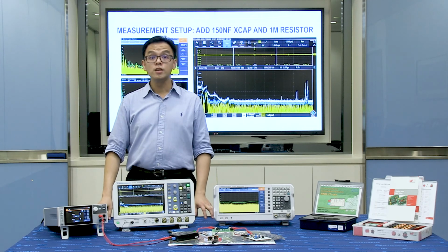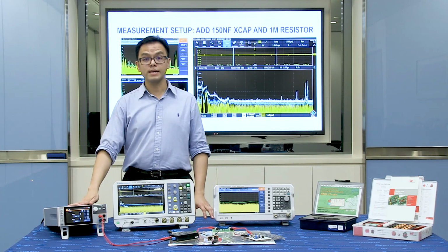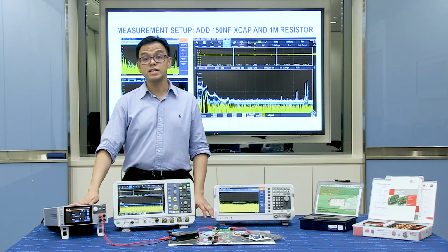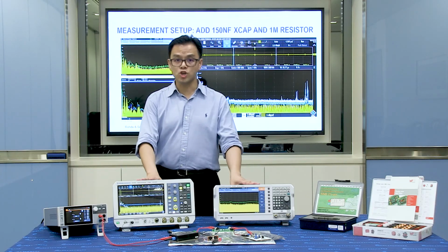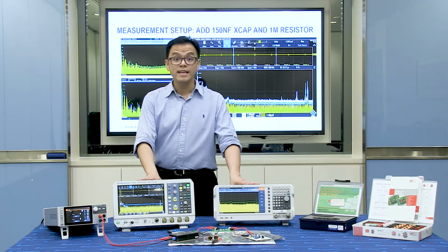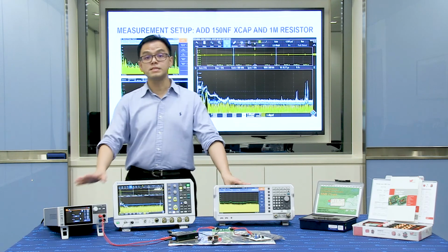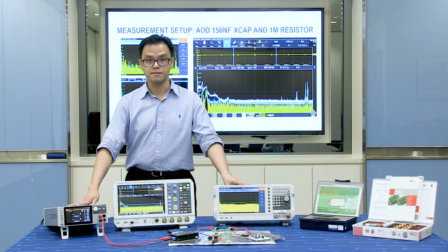In summary, switch mode power supply has big impact on EMI if not designed carefully. Noise can propagate through the circuits and affect its performance. If we delay the testing of EMC to the late stages of design, we may face bigger challenges. While lab equipment like scope and mid-range spectrum analyzer may not meet the CISPR required specification for EMI measurement, they do provide a glimpse into the EMC performance and allow us to make early detection and debugging.